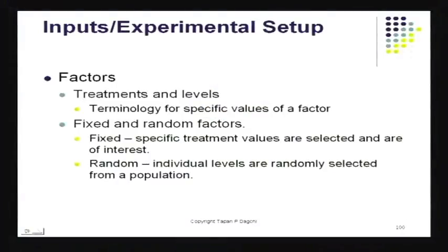But there are, of course, this is a full factorial design. There are other designs which do not require you to run all 8 experiments. And of course, they do not also produce the same amount of information. The full factorial experiment will always produce the maximum amount of information, not only about the main factors, but also about interaction between the factors, factor effect. The partial factorial design, when you choose not to run 8 trials, but perhaps only 4 trials. These are special designs, special matrices that you use to guide your experiment. And these matrices are such, they require fewer trials, but they are clearly not as revealing as the full factorial experiments. We'll see that in a couple of minutes.